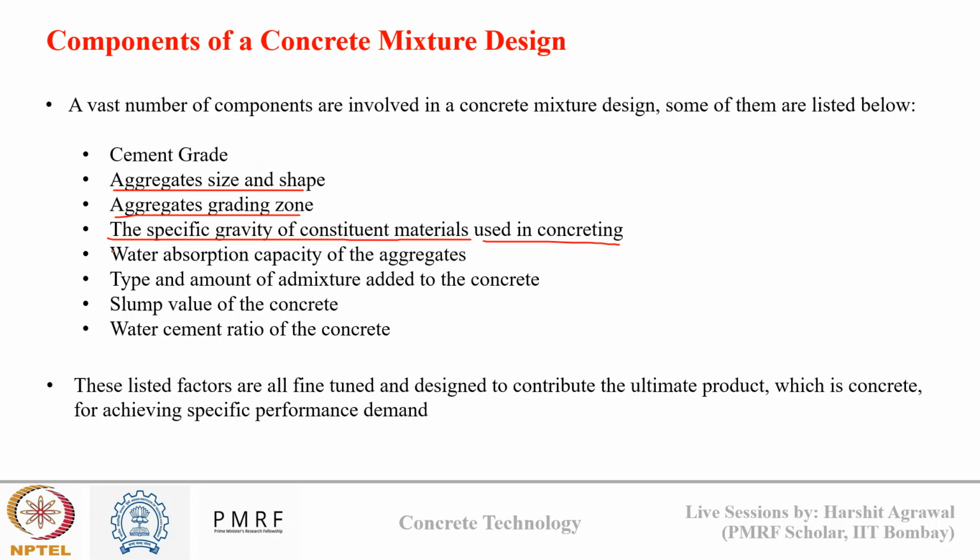Water absorption of aggregate is important because it will help me to keep the W by C ratio the same as what I desired, and it will help me to take into account that extra water that the aggregate is absorbing. Type and amount of admixture added to concrete, like maybe we are adding a super plasticizer or a retarder or an accelerator, will contribute to the concrete mixture design.